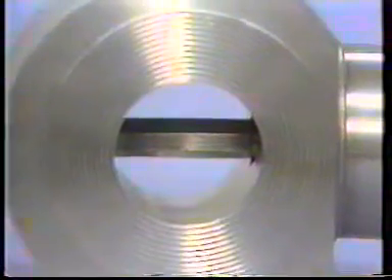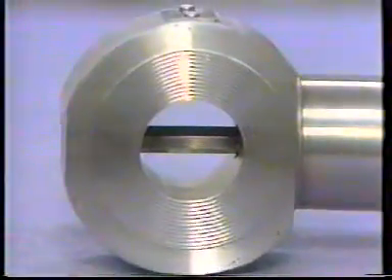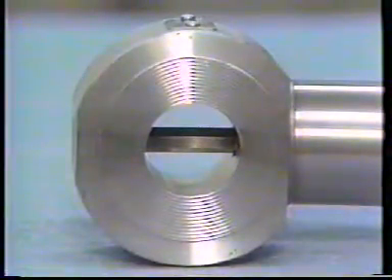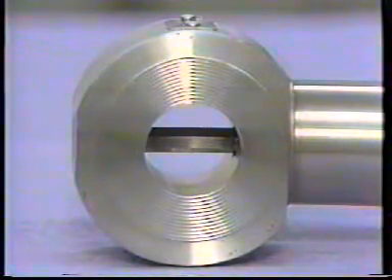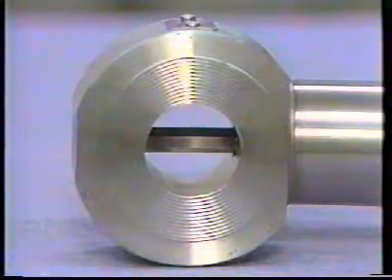The passage of the vortices is usually sensed in two ways. They are sensed by detecting and measuring the fluctuating pressure in the wake of the bluff body, or by detecting and measuring changes in local velocity fluctuations around the bluff body. Vortex shedding meters are fairly accurate in higher velocity liquids or gases. However, in lower velocity fluids or in liquids with high viscosity, accuracy decreases.